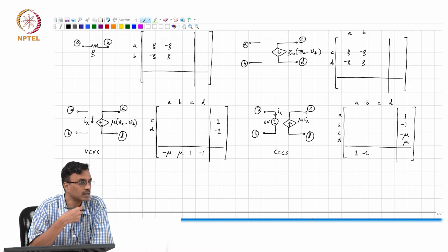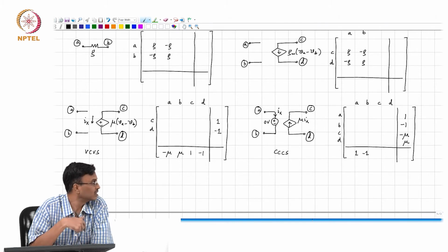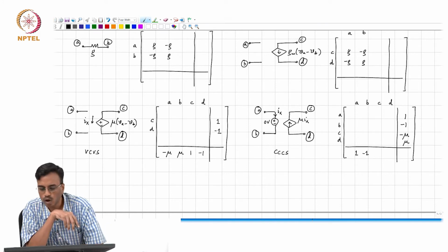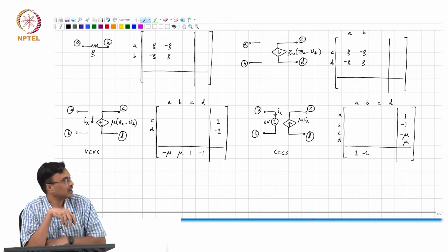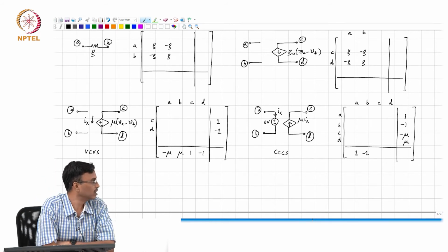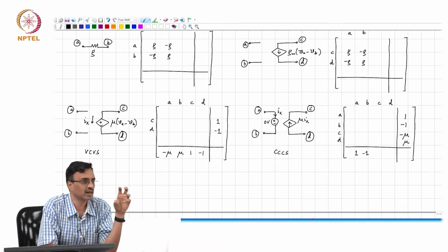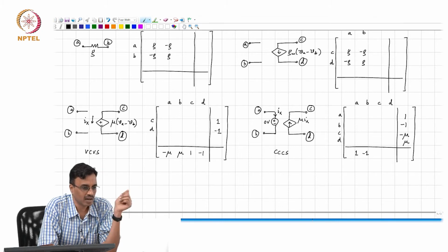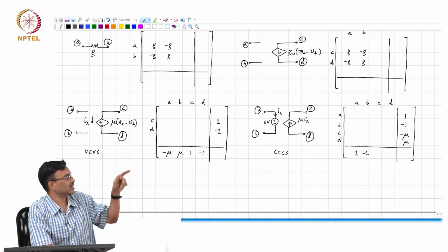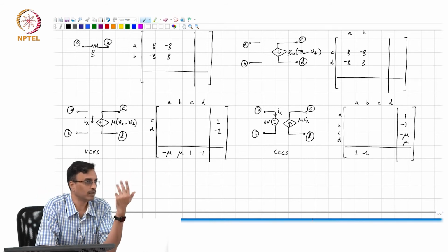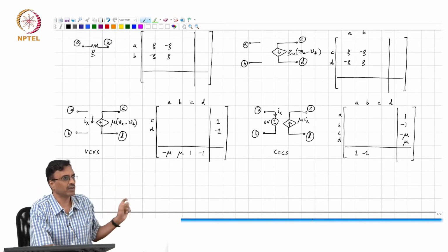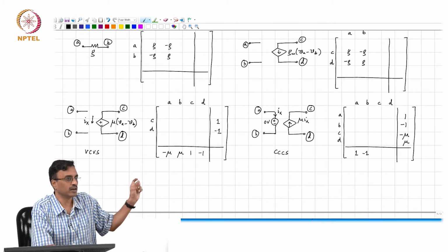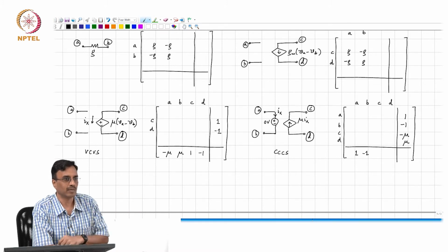See, the assumption in a circuit simulator is that you always measure current through a 0 voltage source. It is also likely that you can have an arbitrary branch current and make mu times Ix a multiple of that arbitrary branch current, in which case it is straightforward to artificially introduce a 0 voltage source and add an extra node there, and the formulation just works.